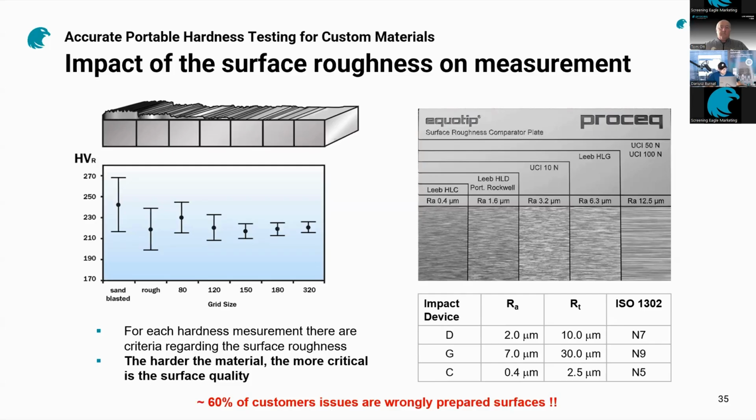I know that we are running out of time. I would like to very shortly answer at least one question. If I have nickel with a modulus of 207, do I need a correction? Short answer, and that's why I want to answer it, is no. It's so close to the reference value of 210, then no. Unless the user is really equipped and wants to apply this fine correction himself, but actually no.